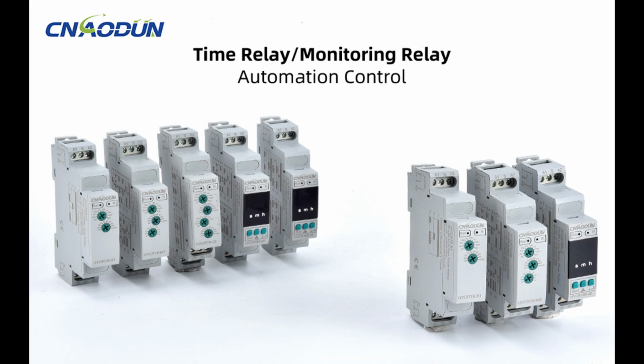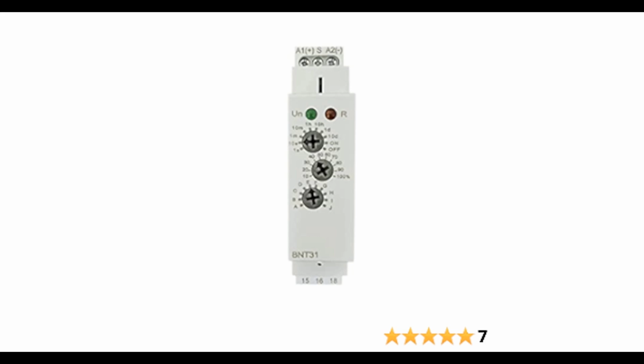Electromechanical relays have physical contacts that open and close to control the flow of current. These contacts can experience wear over time, leading to reduced reliability and eventual failure. Slower switching speed. Electromechanical relays typically have slower switching speeds compared to solid-state relays, with switching times measured in milliseconds or longer. Audible operation. Electromechanical relays produce audible clicks when the contacts open or close, which can be desirable for some applications as an audible confirmation of operation.